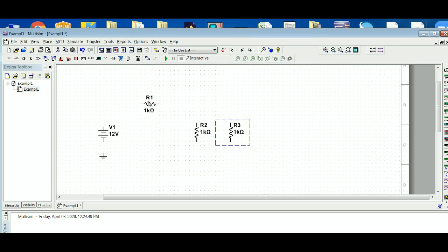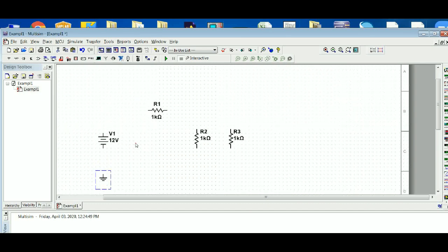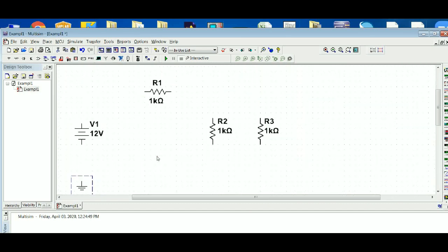So to do this, I guess this looks pretty good. And if you're doing this for inclusion in a report, you want to wire it cleanly. That is to say, without having any loops or unnecessary wires in it. So to do this, I'm going to set my mouse here. Let me make this a little bit bigger again. I'm going to set my mouse here, and I see it turns into a little target there, a bullseye. I'm going to left click it and come up over to this point, which lines up with the R1.